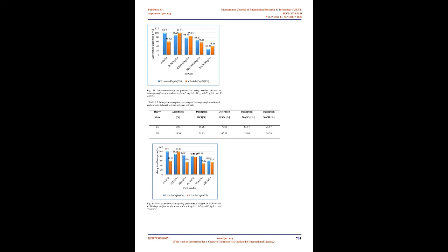[43] G. Effect of adsorbent dosage. The effect of adsorbent dosage was studied ranging from 5 mg to 50 mg of each activated carbon during removal of heavy metals from 100 ml aqueous solution, as shown in Figure 11. This figure shows that with increasing adsorbent dosage, the removal of metal ions also improved from 20% to 100% for copper and 56% for cadmium.